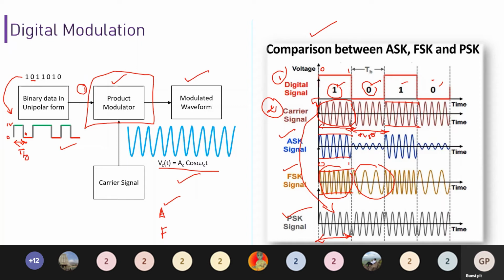Okay, so once we added it, as you can see, the diagram has been tilted. It is a mirror image of the carrier waveform. The starting pulse starts with negative and then it goes to positive. So for this time period, we're going to change the carrier by adding carrier plus 180 degree. So for BPSK, we have to add two phases: one is 0 degree and the other is 180 degree for the carrier.